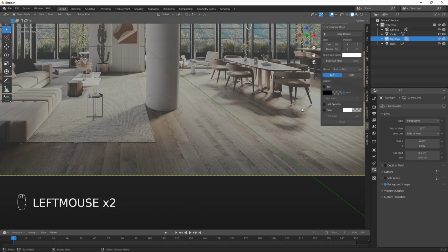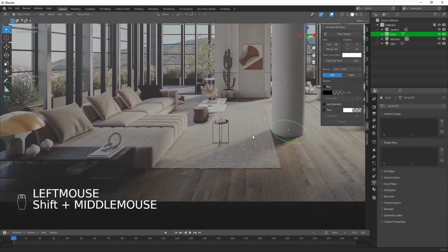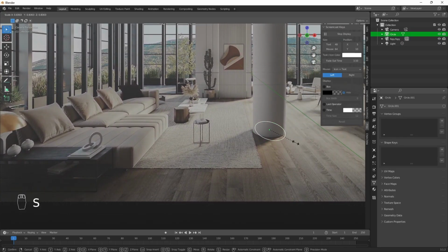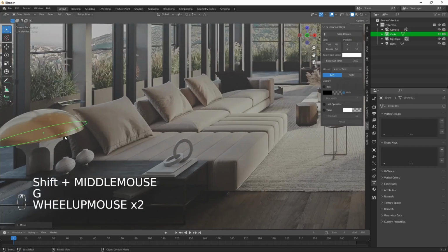Anyways, the only way to find the right value is to keep trying. And although I could do this here with the pillar, it is slightly better to match the shape further from the principal point. And it's because the distortion near the principal point might not be that evident. Usually it's best to do this near the edges, so let's use the lamp instead.